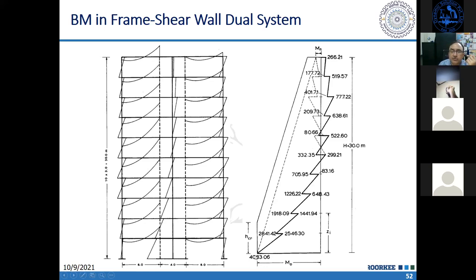So what we have to do, we have to enhance the bending moment diagram. Now this capacity moment, which is used in design of shear wall, is neither available in Indian code nor in Nepalese code. It is there in ACI and Euro code. What is done here is that the sawtooth type bending moment diagram is the original diagram. Then this portion of the bending moment diagram, which is in the opposite direction, we reverse it because earthquake is causing reversal.